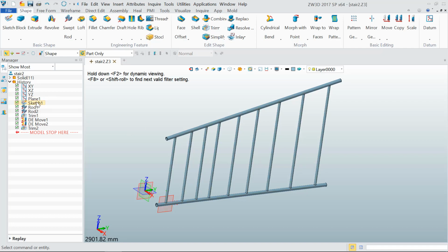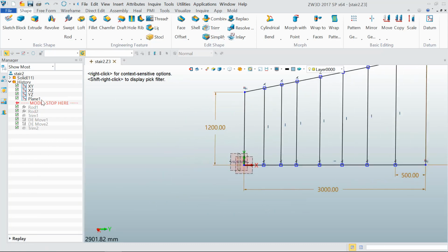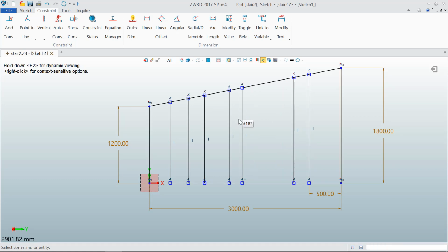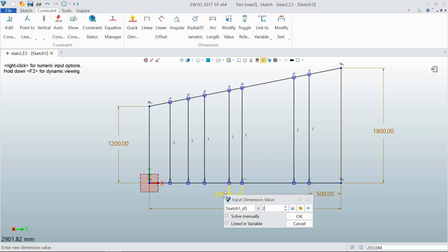again by going back to the sketch. So this is my geometry history. The sketch is here. If you want to adjust the gap, you can right click on the sketch and click redefine. Now here we can adjust the sketch again. Probably we move this closer to this left member so that we can notice there is a significantly larger gap in between here. And we can also put some dimensions to make a precise adjustment, for example 200.